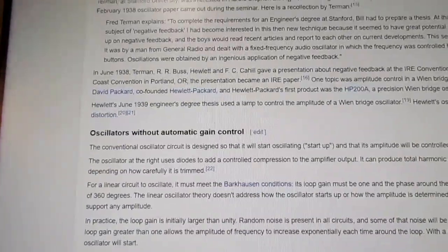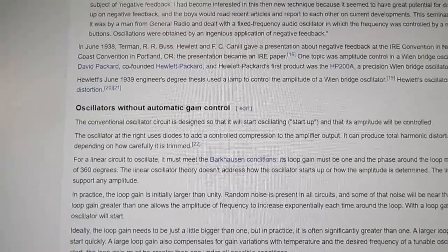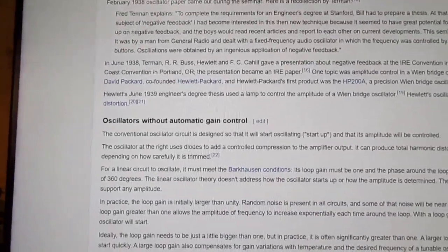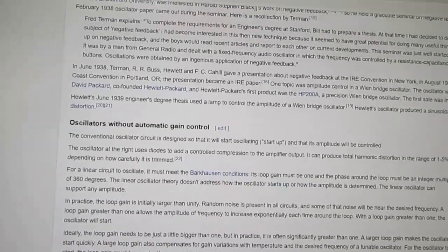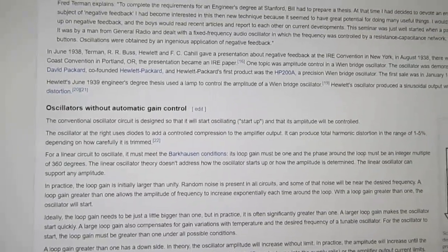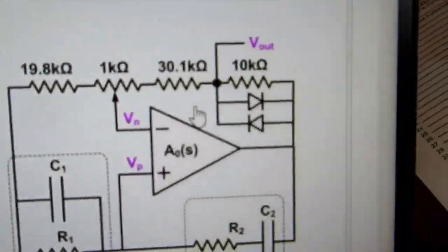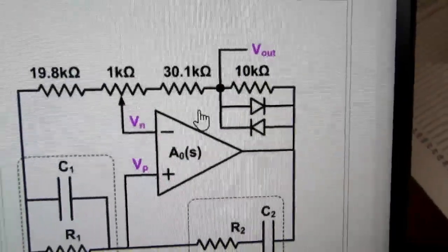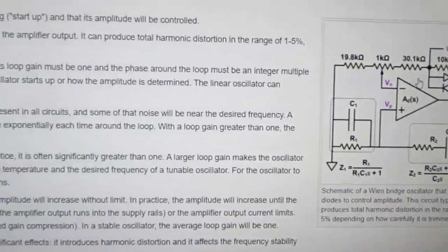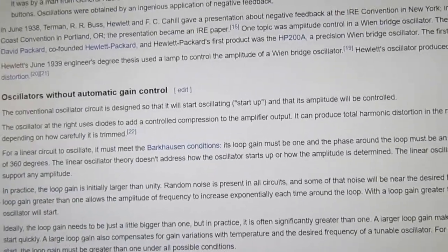So actually, it's a nice article in here, and I've built these before. I used to build audio equipment for recording studios and radio stations a long time ago, and I often included a 1 kilohertz sine wave oscillator based on the Wien bridge oscillator circuit using an op amp, and I actually used back-to-back diodes as my stabilization component, but in this kit it's using back-to-back LEDs. Similar result.